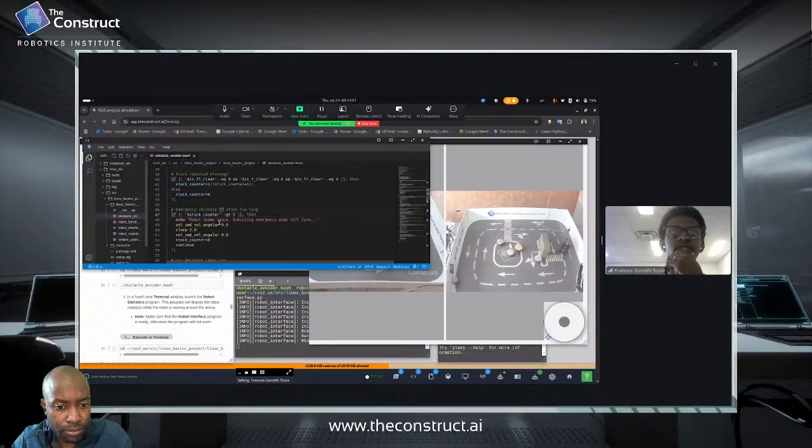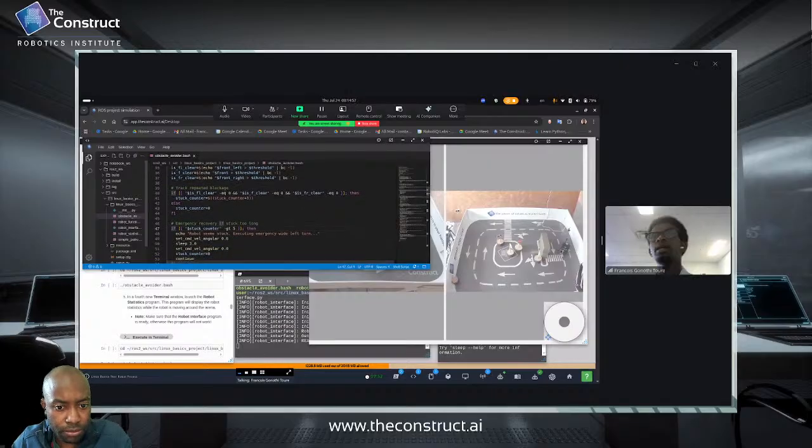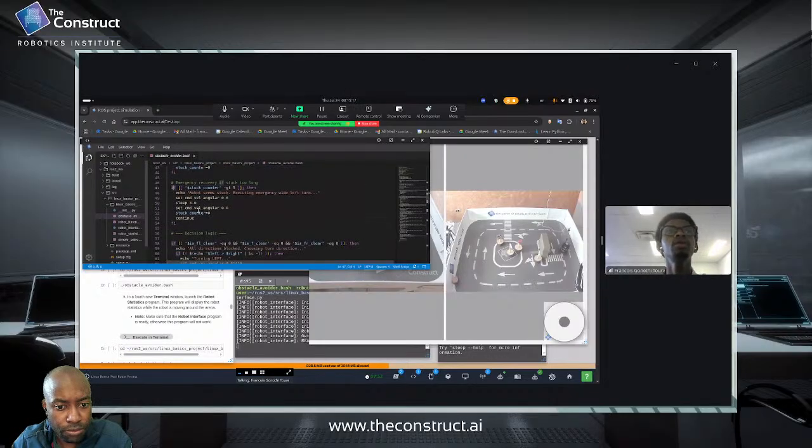Basically, as you can see here, after we've done the clearance calculation, it tracks the repeated blockage, right? And at some point when I was running the code on the real robot, it came until here. I think this is a break, and then it was moving. It took several seconds before making the decision to turn either left or right. So when it tracks the repeated blockage, it will launch this emergency recovery if it's stuck for too long.